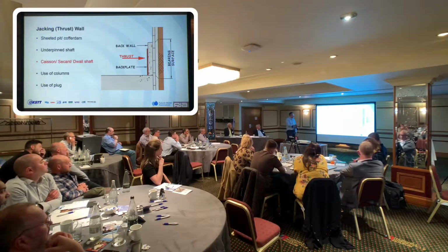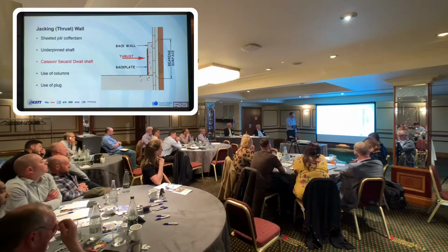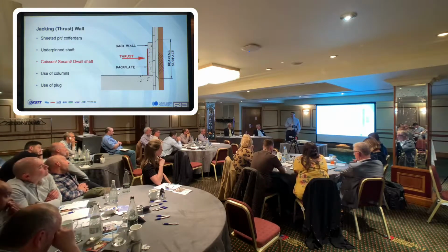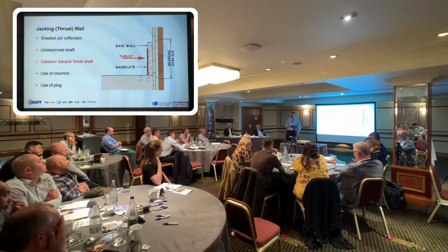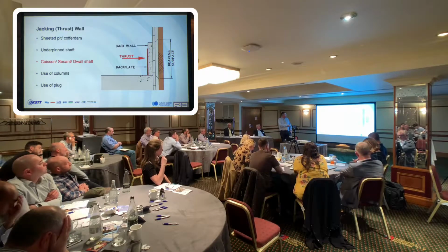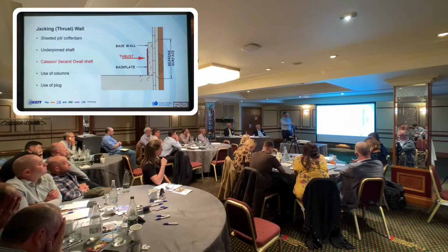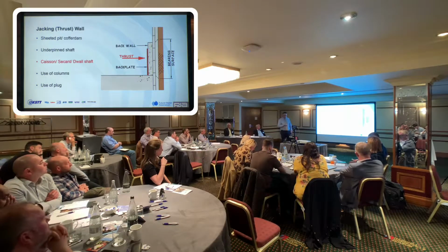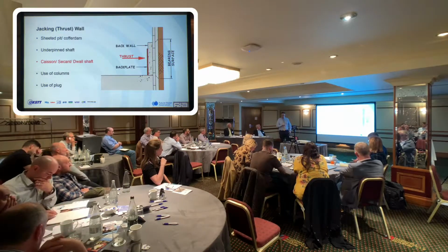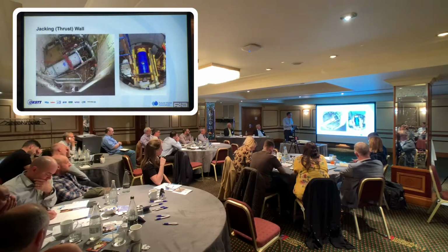And in tandem with that, which would apply to all of these methods, remember you need to look at the loads that you're dealing with if you've got surfaces behind you. Any load coming down through there into the back wall ultimately gets pushed out. So if we've got, for example, a high pressure gas main sitting there, you need to be thinking about that, and possibly designing the back wall in such a way that it could take a lot more load.